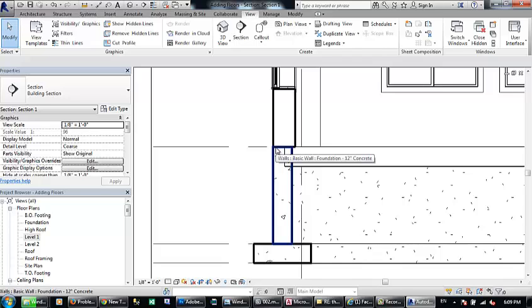Again, the question was, would you like walls that go up to this floor level to attach to its bottom? Bottom means it will stop here at the bottom of the slab. And this is something not desired at all, because this is kind of a bearing wall.